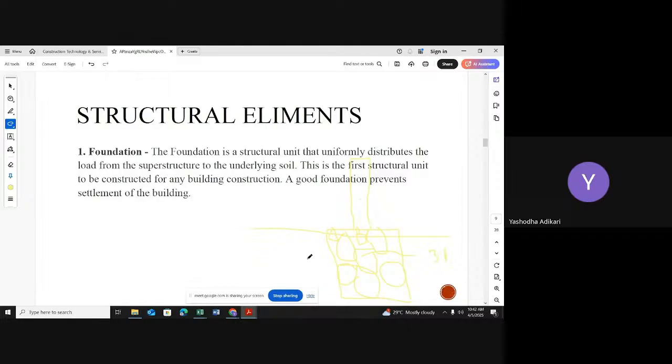Imagine you have constructed this wall by using bricks. The foundation is always wet because it has already absorbed water. What will happen? The wall also absorbs water from this touching surface. Wall also can absorb water from the foundation. So what will happen? The brick also absorbed water. Normally we are finishing the walls with paint, with a putty layer, right? So if the wall absorbs water, it totally affects the whole building structure, the appearance, and it damages the final paint. A lot of disadvantages are there, right?